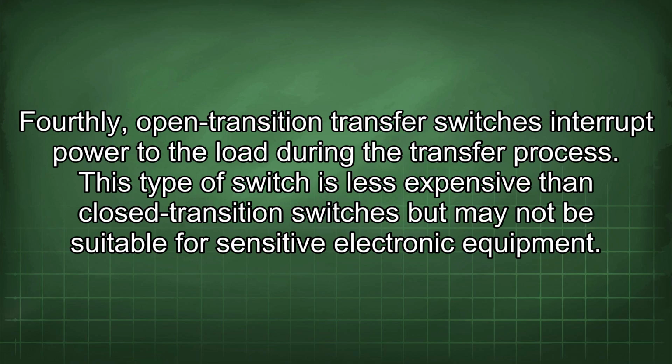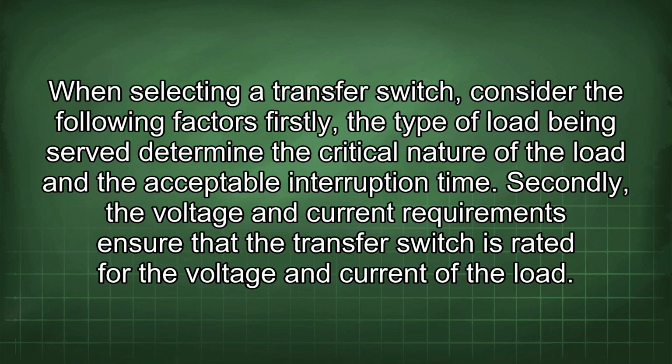This type of switch is less expensive than closed transition switches but may not be suitable for sensitive electronic equipment. When selecting a transfer switch, consider the following factors. Firstly, the type of load being served. Determine the critical nature of the load and the acceptable interruption time. Secondly, the voltage and current requirements. Ensure that the transfer switch is rated for the voltage and current of the